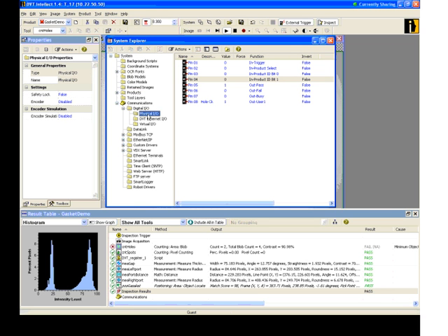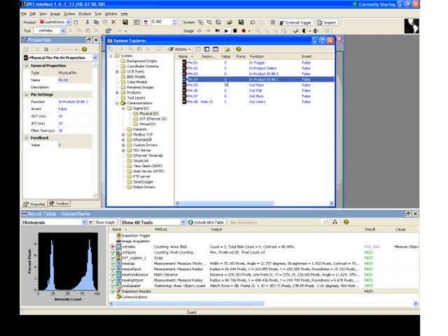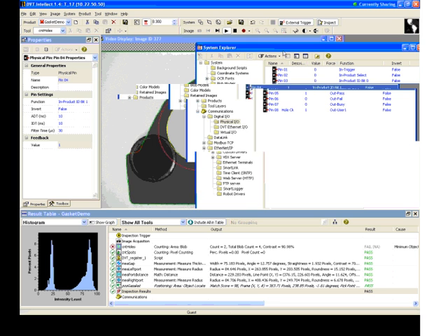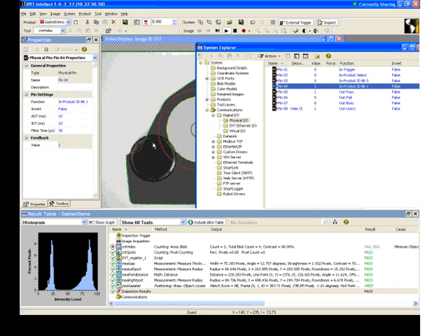I could physically connect to the camera right here and select a bit right here. Bit 0 is low, this one right here. I'm going to use a technique in this camera rather than physically go over there, so that you can see it. I'll do it here. I'm going to force this bit to high. So that's bit 1. So this is 0 or 1, this one will be 0 or 2. As you see, we have all these sensors on our gasket. I'll take that one off and go ahead and trigger that so everything's passing on that one.